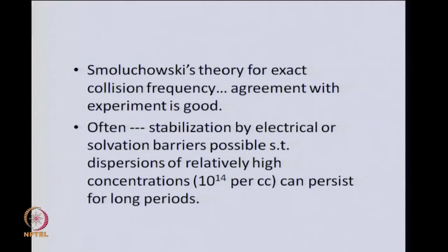I will try to simplify the picture as much as possible, but we can alongside look at the more rigorous derivation also. Before we do that, let us think of the practical part of it. If we have such rapid coagulation systems, in practice you may not always want them. After all, the dispersions may have to be processed over certain lengths of time. You might not want these dispersions to break down very quickly, and many products will require the dispersions to be metastable, as stable as you can practically have.